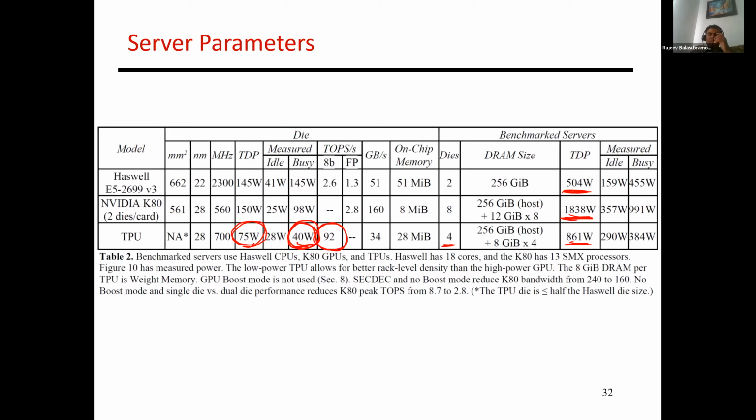Yeah, and there's this good question about the ops per weight. I should have answered this question long back, but it kind of got buried in this list. The ops per weight are indeed affected by the depth-wise and the point-wise convolutions that we looked at. And yes, it may impact the ability to meet the peak throughput of that particular accelerator. It reduces the number of computes, but because it reduces the reuse as well, it may have an impact on the peak throughput and the energy efficiency. So that's a really good point.